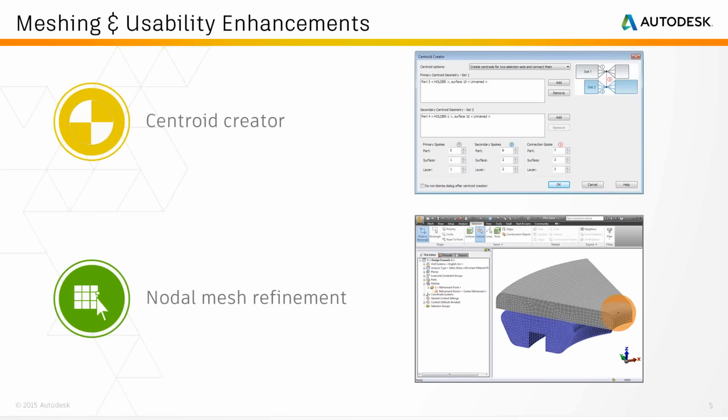If you make all those changes and then decide you want to change your mesh size, you would lose all those changes from before. Whereas in the 2017 release, with all this improvement, all the part numbers, surface numbers, and layer numbers that you assign to spokes are associative, which means after remeshing they are retained. Yeah, because it's not an afterthought here, it's from the very beginning. When it goes out to create all these lines, it's using all these parameters over here.